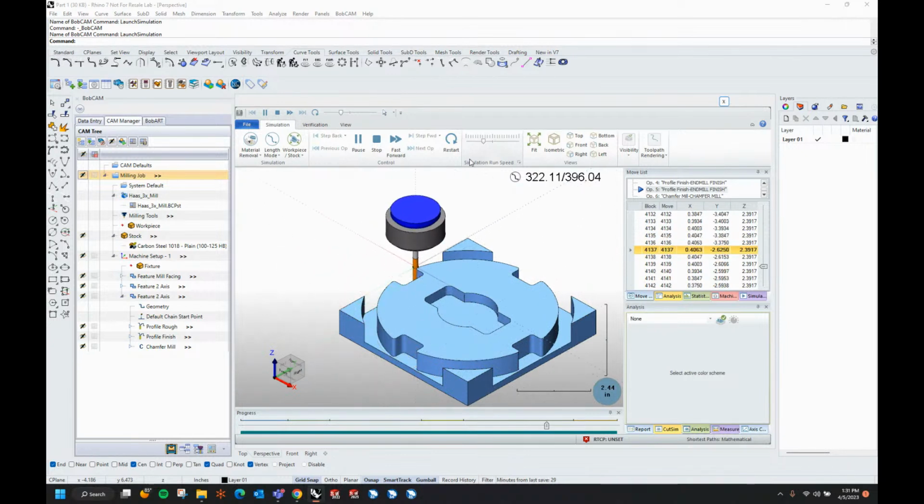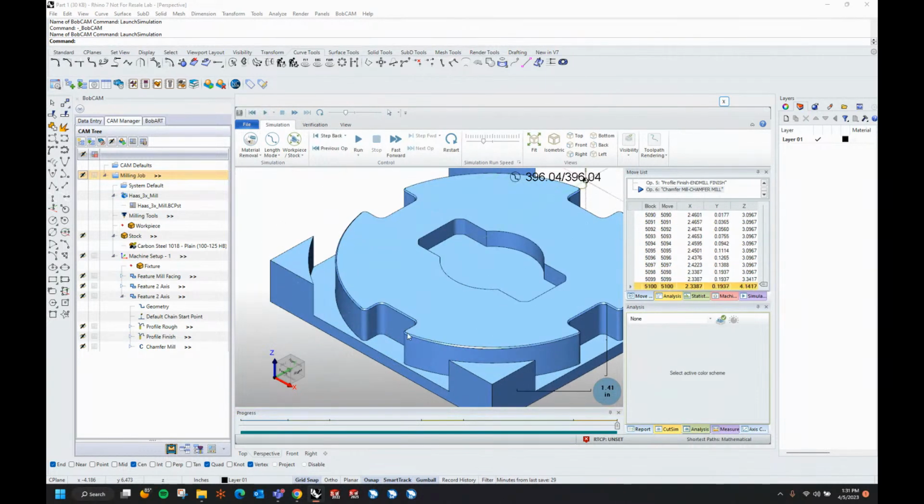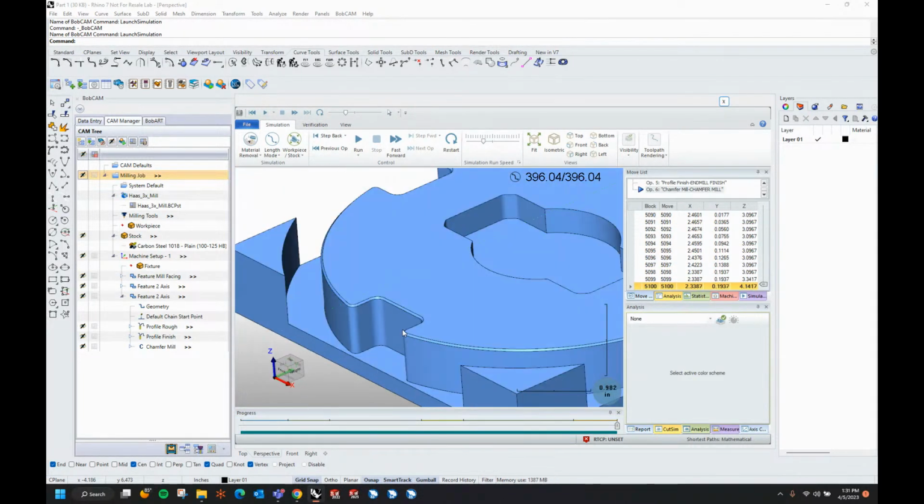And it should go around one more time without retracting because I got the spring pass on. And now my chamfer. Now, keep in mind when you're running simulation, it does run at a lower resolution. Once it stops, these areas that are kind of jagged do clean up.